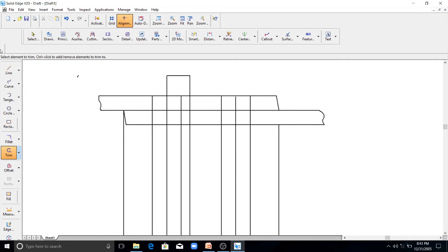Now you have to draw a line from this diagonal to this diagonal. In order to draw the diameter of the snap head, you need to bisect this line, and this bisector should extend till it touches the center of the rivet. So bisect this line first.